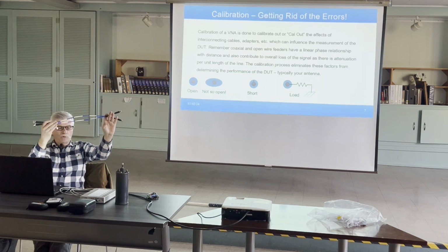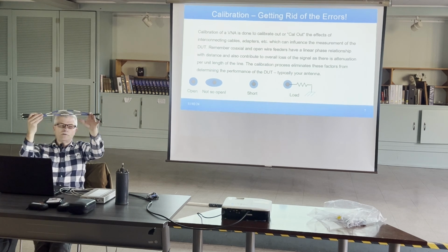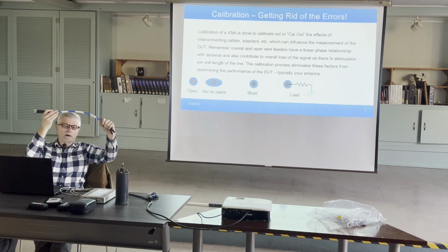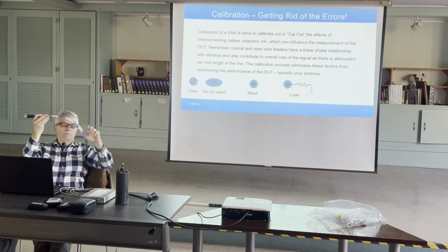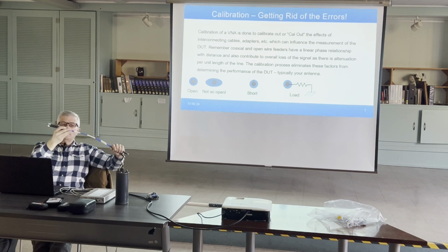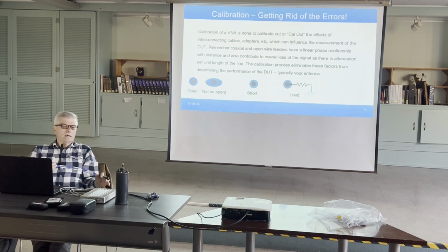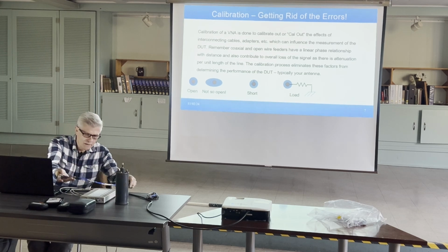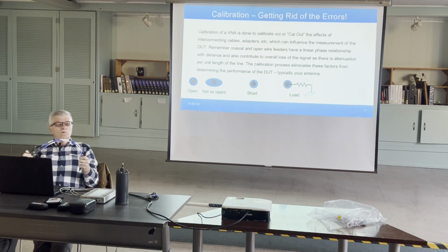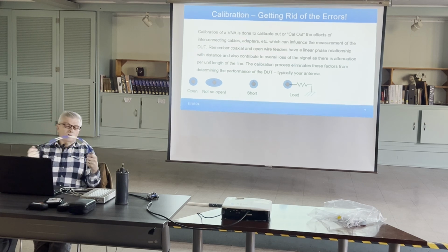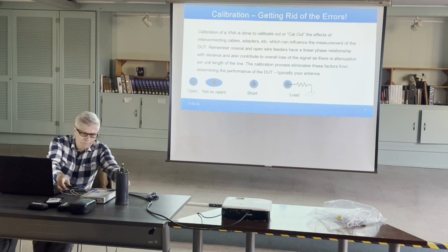So these cables would be included, and if you're doing anything with your Rig Expert, by the way, you really need to put the Rig Expert at the load. Otherwise, you need to calibrate it with the cable involved. Otherwise, you're really not getting the full picture of what's going on. Now, there are times when you do want to include the cable in the measurement because you may want to determine whether the cable is good or not. Okay, so there's two cases for that.